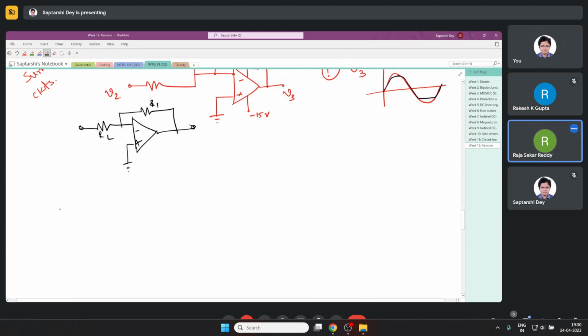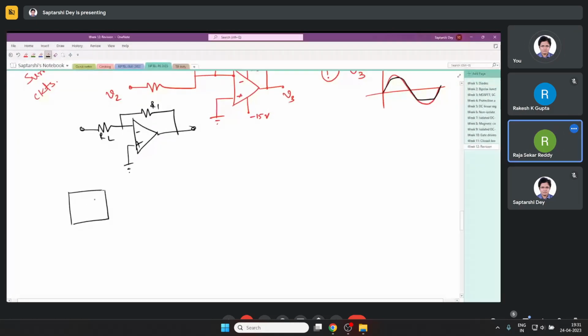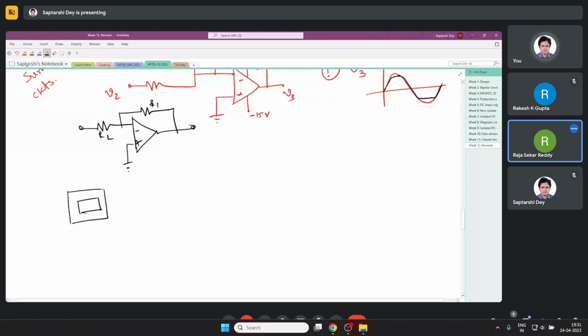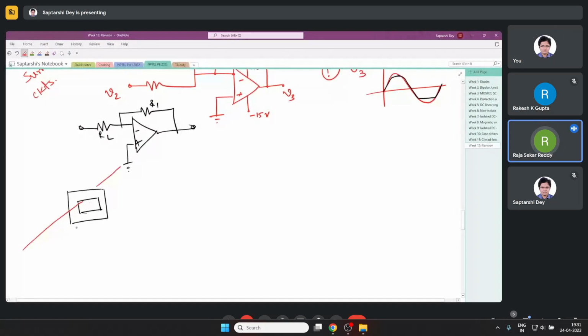I had a switch reluctance machine, which I had to control. So the current I had to sense. There was a current sensor like this, and I kept the wire through it. This is the wire going through the current sensor. You can understand how it looks, yes? Inside, and there are leads. I have given supply to this, and from here I am getting the signal.